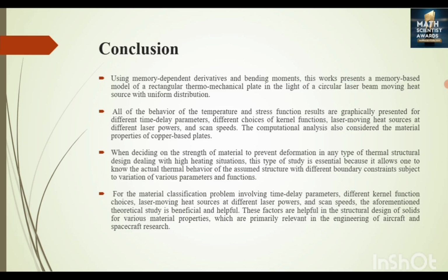Using memory-dependent derivative and bending moments, this work presents a memory-based model of a rectangular thermomechanical plate in the light of a circular beam moving heat source with uniform distribution. All of the behavior of the temperature and stress function results are graphically presented for different time delay parameters, different choices of kernel functions, and laser moving heat source at different laser power and scan speed. The computational analysis also considered the material properties of copper-based plates.